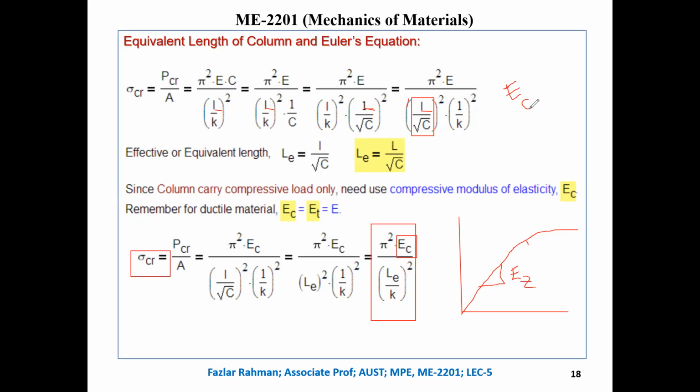But in the real world, they give a material's values for both. If you are working in the aircraft industry, a missile defense industry, or a shipbuilding industry, then you see the value of E is not the same. Compressive and tensile are a little bit different.